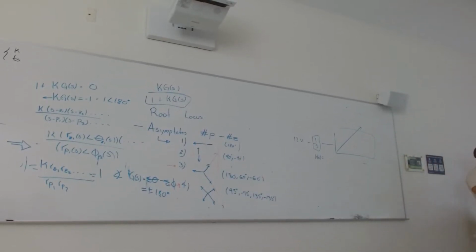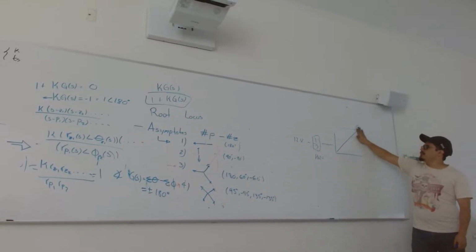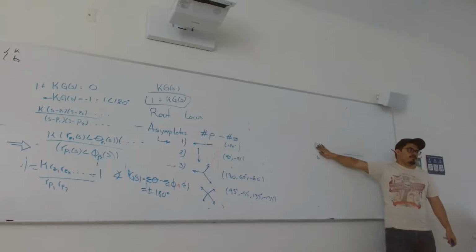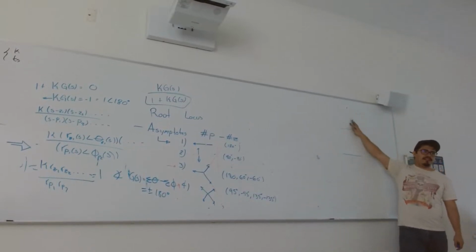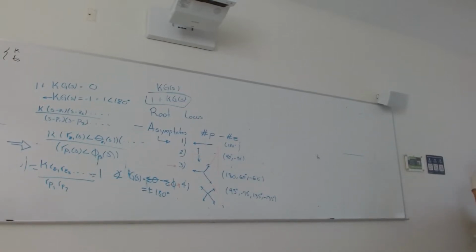You need to add energy to the system to keep increasing in value. And actually, to have a true perfect derivative, you need an infinite amount of energy. Eventually, for example in a plant, once you hit minus 24 volts, you saturate. But the idea is, at least for that range, it is perfect, and usually you design so you don't go out of that range.